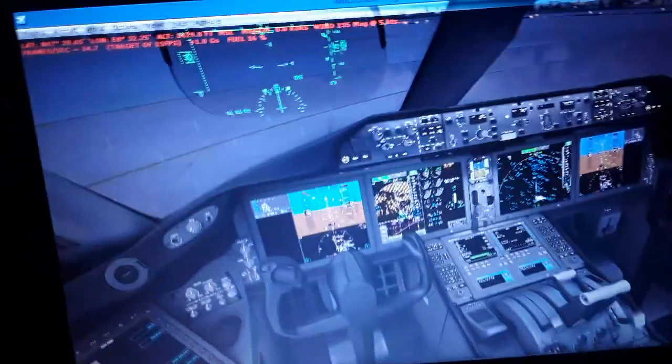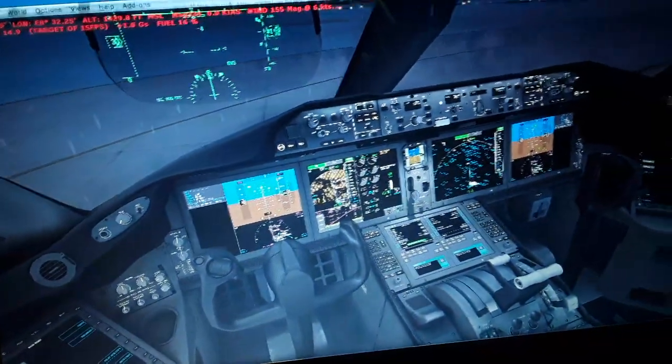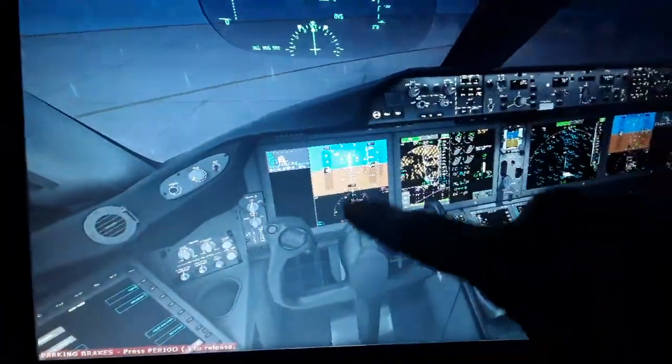So we have also the flight director crossbars for manual guidance of the aircraft and the autopilot crossbars for automatic guidance of the aircraft. We have also, as I told you, the angle of attack of the aircraft as it flies, the standby instrument display, the integrated display with the flight plan, and the HSI, the horizontal situation indicator. You can see it in the primary flight display over here. We have also the flight modes with the autopilot and the autothrottle, and later the vertical navigation modes.